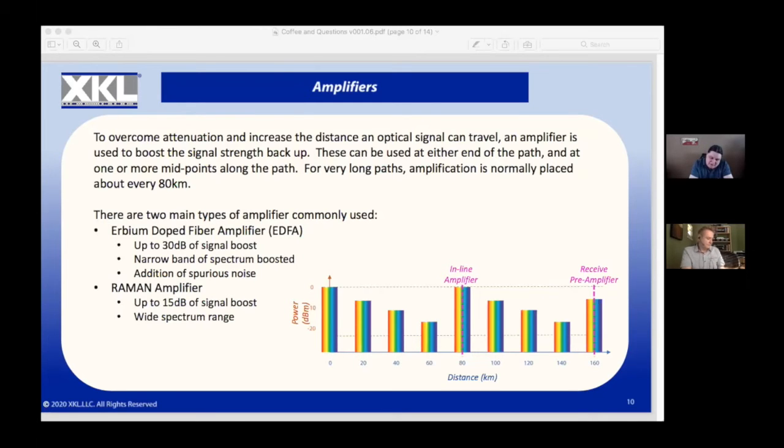Now the other amplifier, I'm getting a little bit distracted here with the notes and things. The Raman amplifier is actually named after the scientist who worked out all about the spectral scattering effect of combining different signals in a medium, because it's not just an optical thing, and how the scattering effect of other signals can stimulate the energy in another signal.